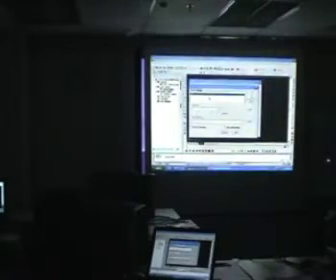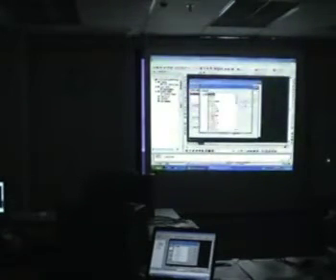Now the third one, I'm not going to take z, because if we take the z value of the text, we're actually taking the absolute value of that z, which means, for example, if the text was placed at 0, we're going to take 0, which is pointless. We don't want that. What we want to do is take the text value. If it's 44.59, it's going to appear as 44.5. That falls under the property string. String? Yes, it's under string.